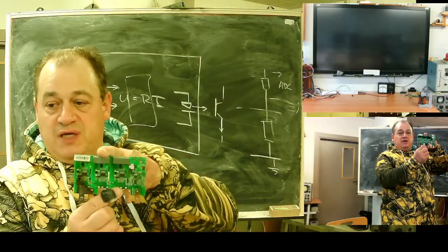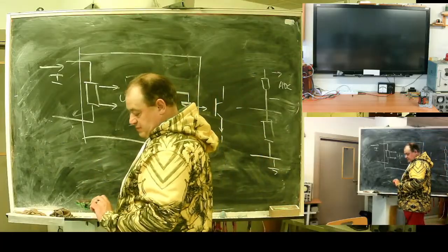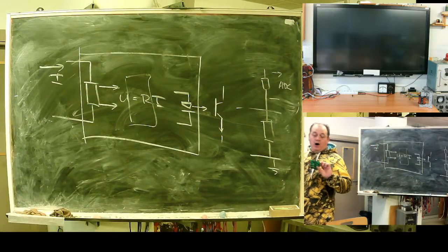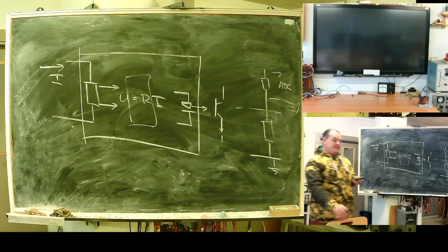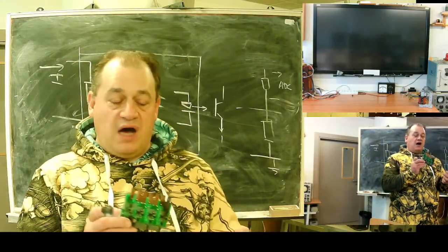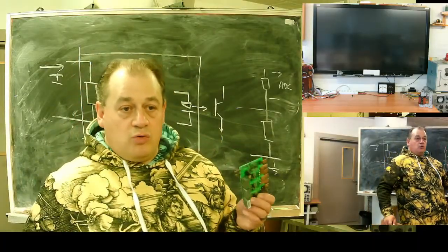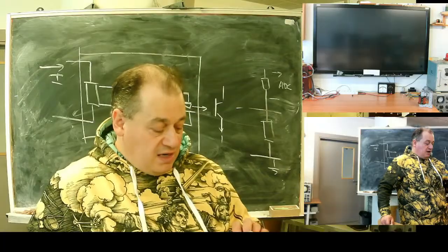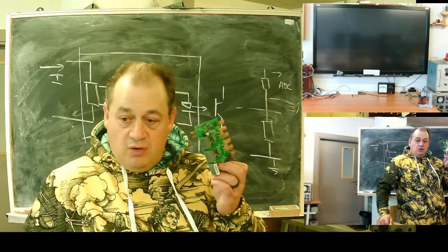It's used to obtain power. Each island, here we have 3 islands, has its own power and its own voltage signal, its own current under its potential. All these 3 blocks are hot. They only calculate energy. So results are sent by some kind of communication protocol via optocouplers.